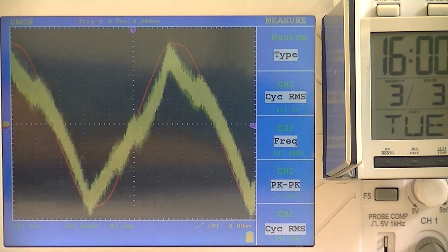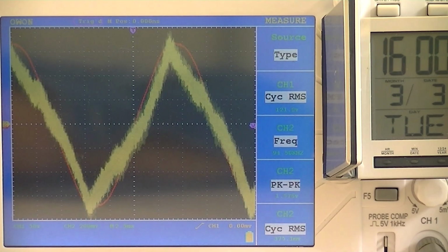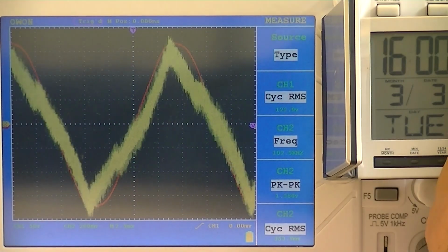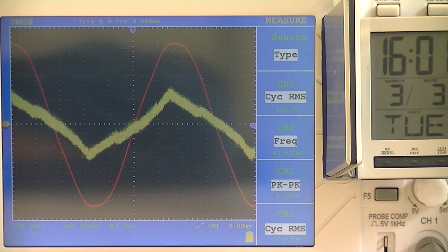And you can see it going up and down as loads are getting switched onto the system. And that's pretty typical for my grounding system. So I'm just going to change the scale one more time. And it's reporting 370 millivolts on the RMS, and we have a peak to peak of 1.5 volts on my grounding system. And today that's actually quite low.